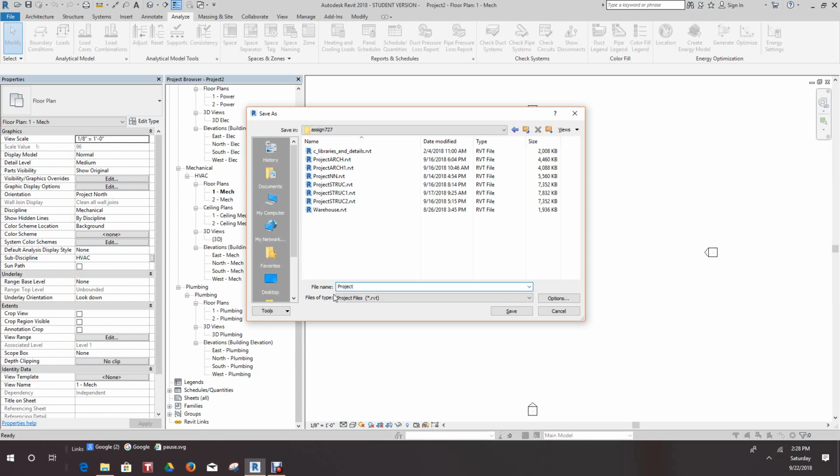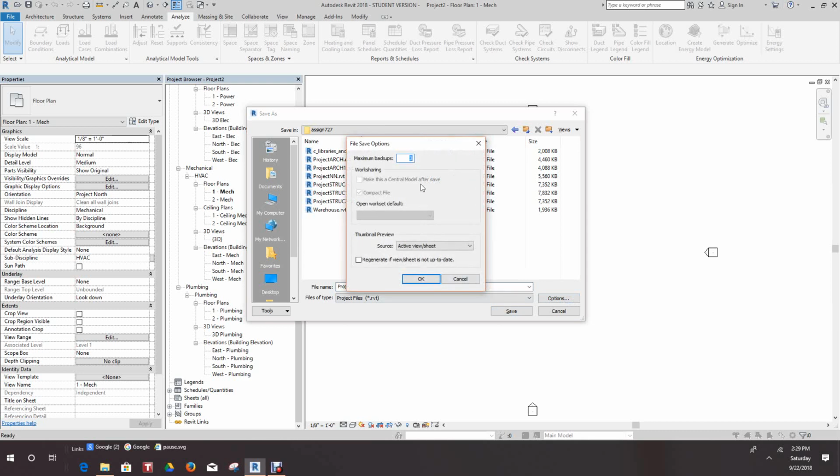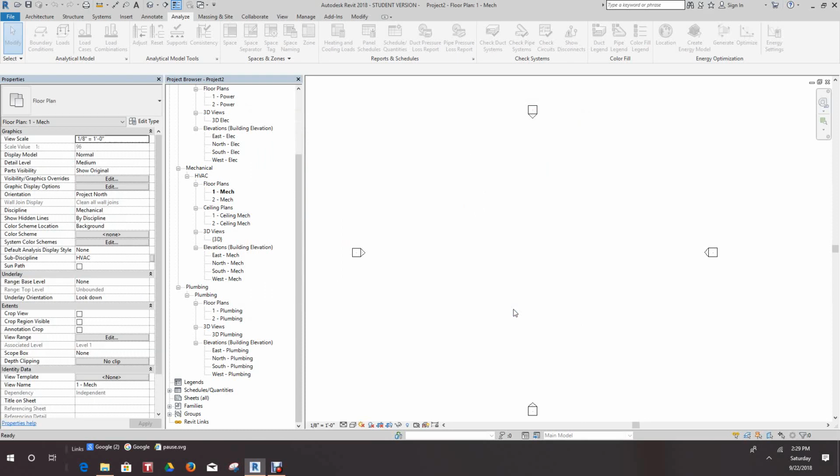So this is going to cover electrical, mechanical, and plumbing. So yeah, I thought initially we would use electrical, but let's just go with this system template, so we can have all these things already set up. Then we'll take our options, and we'll change this to 1, okay, and save. So there we have our mechanical or our systems project basically set up.